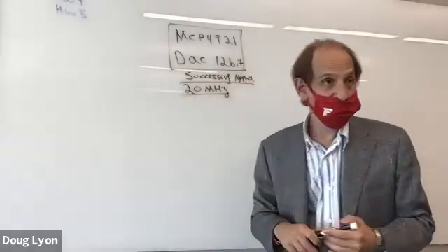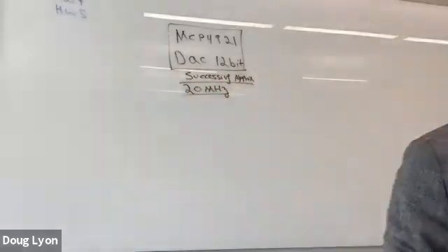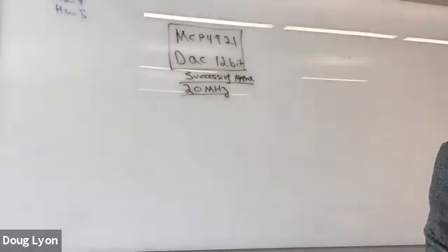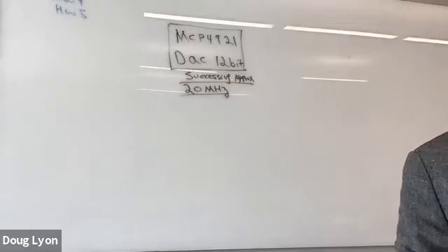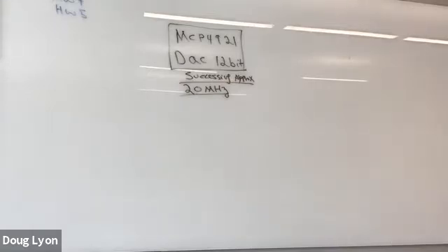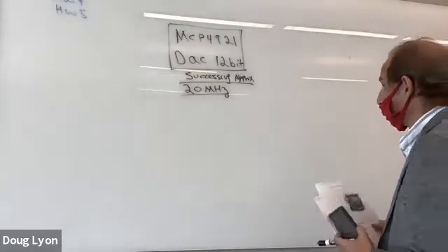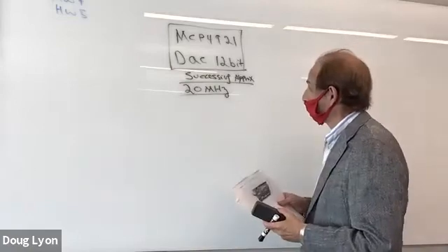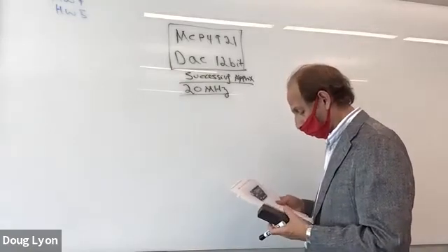In other words, it has nothing to do with the Arduino Uno's maximum rate. What does impact the maximum rate that you can output is how fast the Arduino Uno can pump data into the DAC. Now that is something that's going to affect our sampling rate when we do a waveform reconstruction.